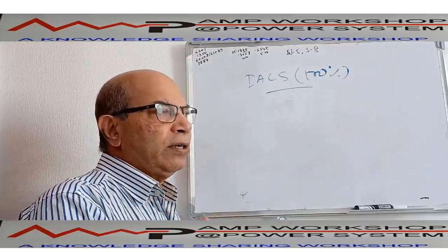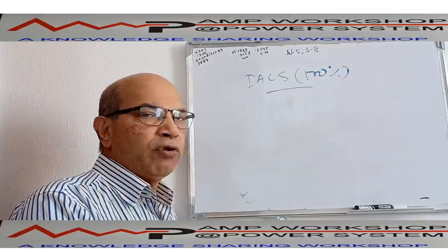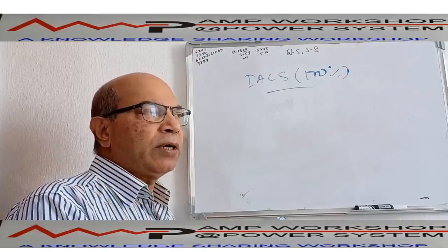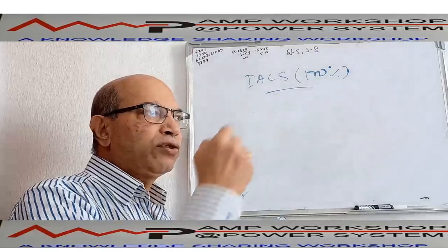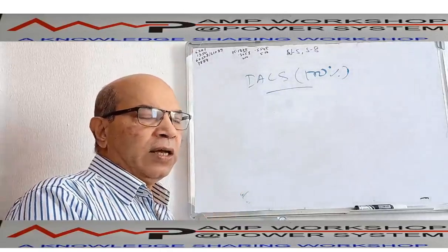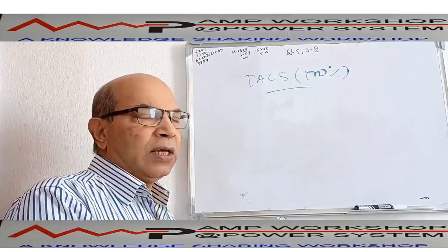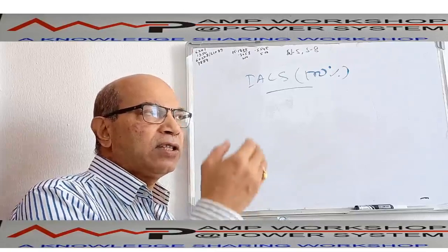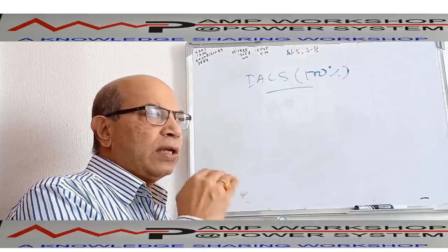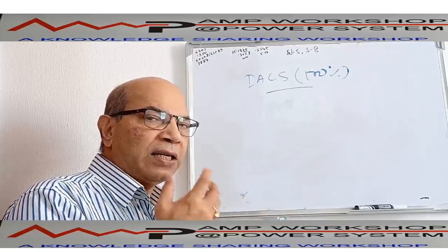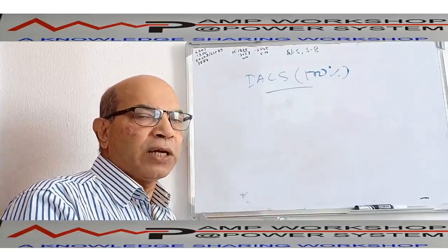When we select any conducting material for the overhead conductor for transmission and distribution, a couple of properties need to be looked into. Number one is conductivity, which gives a high current carrying capacity. As the conductor will be strung between two towers, we need mechanical strength; if it has poor mechanical strength, it can snap. Then it should be lighter, because otherwise the sag will be very high. If the sag is more, heating will be more and voltage drop will be more. If the conductor is lighter, the sag, or deviation from the normal level, will be less. That is also one of the requirements.